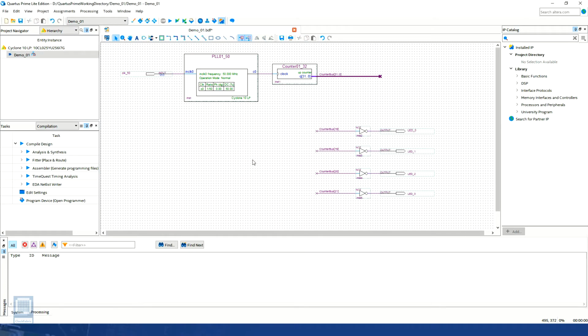We can change the names of the instances of the symbols present in the design by double-clicking on the inst label like this. This step is not mandatory for small designs, but in a complex design scenario, these instance names might play a very important role in documentation and collaboration. At this point, we're done with our schematic design. Now all we need to do is analysis and elaboration of our design before moving forward.